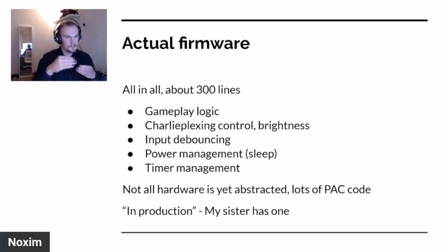When you go into sleep, it pauses your program execution, but it also resets some of the peripherals. For example, the GPIO stuff gets reset between sleep states, so you have to reinitialize it.